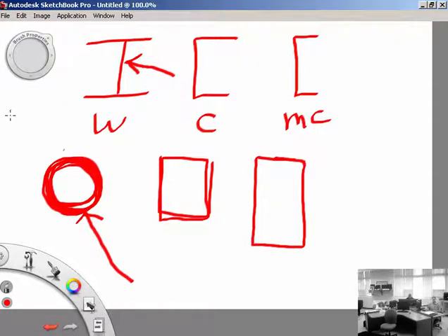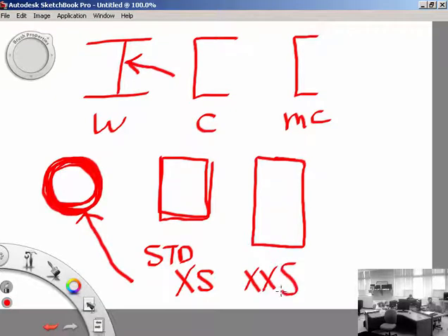But pipes actually come in various forms. So they come in standard. So you go say 6-inch pipe, that's going to be your standard wall thickness. Then you've got an XS, which is extra strong. And then you've got a double XS, which, as you might imply, is double extra strong.